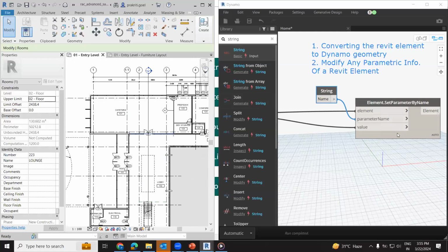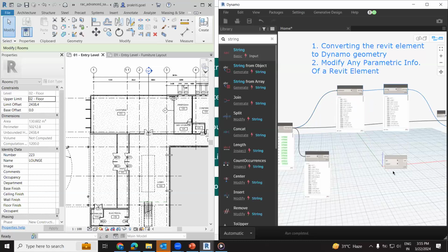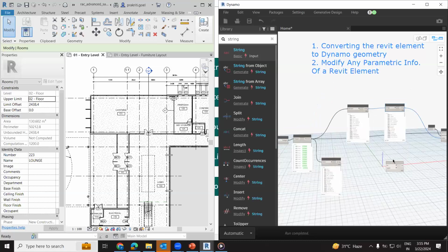right? So I have created one script for these rooms, right? Now the same script I can use for multiple purposes, like I can provide the upper cases for views, right? So for that we can convert it to a Dynamo Player worthy script. For a Dynamo Player worthy script, you need to provide input and output, just like Google Forms, when you registered for this webinar, right? So you had a form, right? Those information you had to provide, and output was the webinar link.